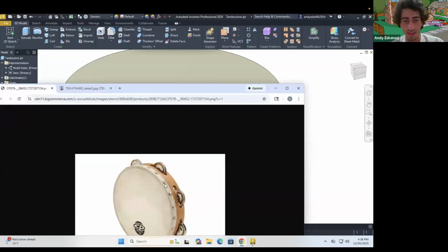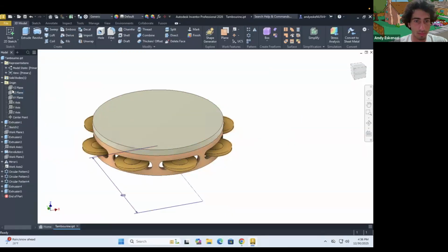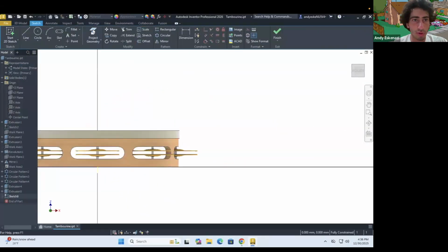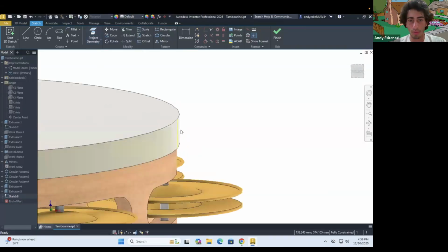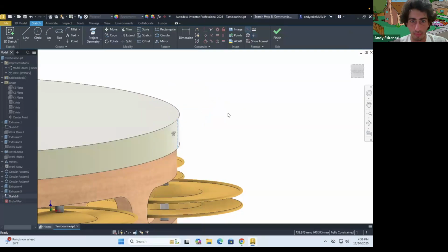But let's add these last details, which is those little circles. So how would you do that? Well, it's a very simple thing to do, because I'm gonna go back to, say, that original sketch. I'll do a sketch on that face in there, and all I want to project is that little line. So I know that is the line where we're gonna work from. I'm gonna make that a construction geometry for now.